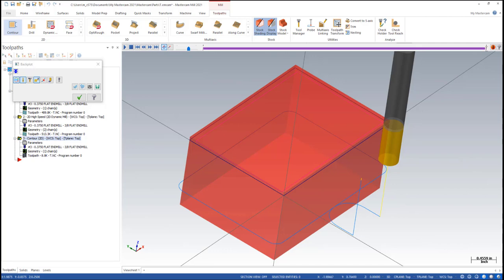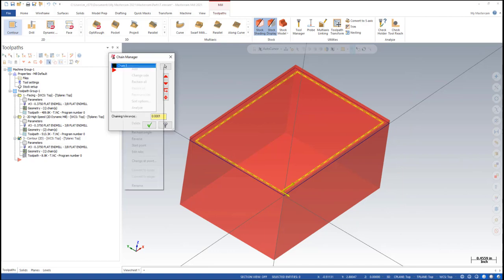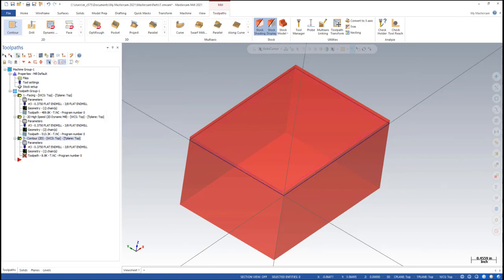You always want the tool rotating in a clockwise method, and then biting the material and climbing through it. You imagine the flutes biting in, and then the direction of the feed is in the direction that we want it to be. So we'll go and change that back. So just reverse, and okay.